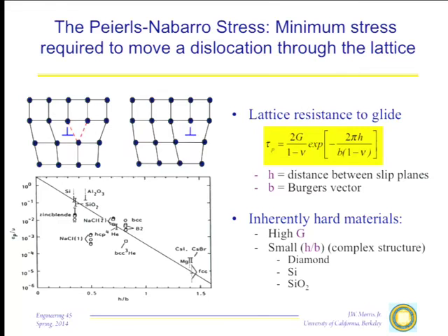The problem with these materials is while they are relatively very strong, they also tend to be very brittle for reasons we'll talk about a little later, and for that reason have very limited engineering applications. You don't make many structures out of glass for fairly obvious reasons. It breaks. Not that it isn't strong, it is strong, but it breaks. Therefore, you don't use it that much. You use materials down here, which can be both strong if you treat them right microstructurally, and also can be tough and resistant to fracture.